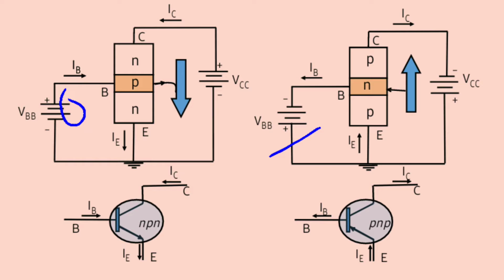In order to describe fully the behavior of the common emitter configuration, we have to consider two sets of characteristics: one for input or base emitter circuit, and one for output or collector emitter circuit. The output characteristics are plotted for the output current IC versus the output voltage VCE, for ranges of the input current IB in both transistors. The input characteristics are a plot of the input current IB versus the input voltage VBE for a range of various values of VCE.